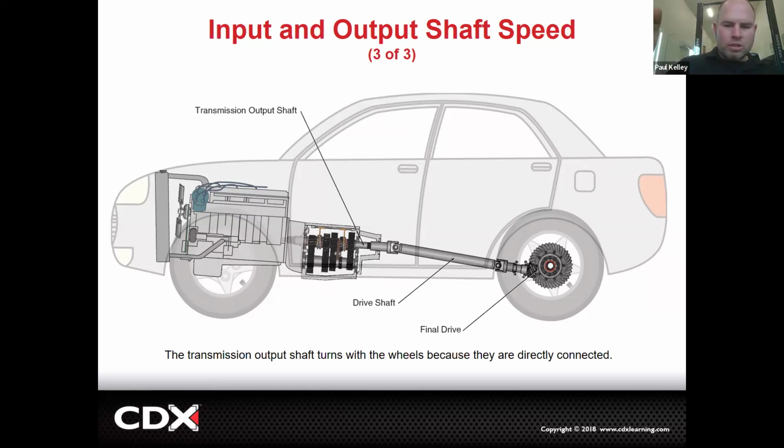When I try to go into neutral, it feels like it's blocked. The reason it's blocked is because the shafts in the transmission are still turning because the clutch isn't completely disengaging. I'm throwing the pedal all the way down, but it's not completely disengaging, right? So the test for that is very simple. Turn the engine off. If it shifts good in first, if it shifts good in reverse, easy, easy, easy. But then you start the engine and now it's harder to hit first and harder to hit reverse. That's because that clutch is dragging. In other words, it's not disconnecting all the way. That's an ASE concept you have to know.